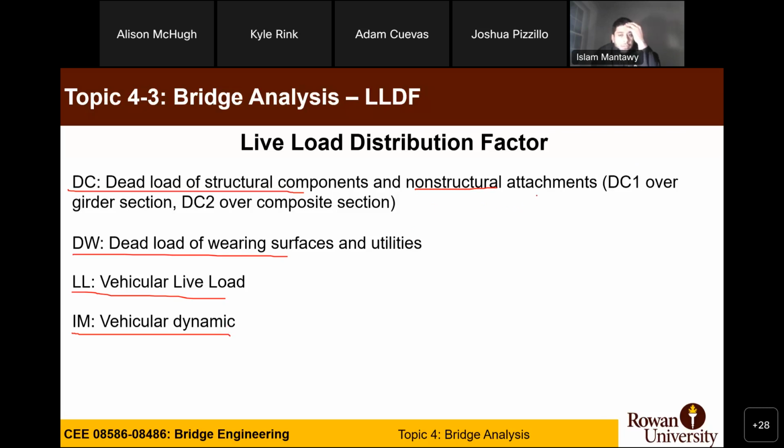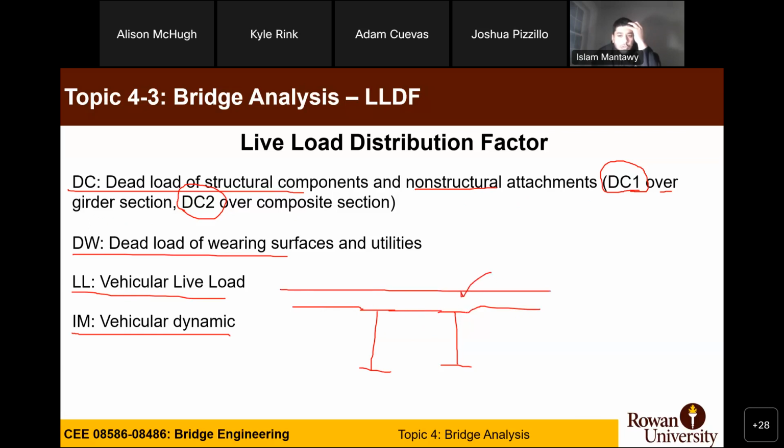The only thing that is different from the last few weeks is that we now have something called DC1. I don't discuss the difference between DC1 and DC2. There is some verbiage here on the difference, but if you assume this is your steel girder, and you have a bunch of them, correct? And you have a bridge deck that you're gonna cast concrete into using formwork between the girders, and the weight of the concrete, because it's still wet, will be transferred to the girder, correct?